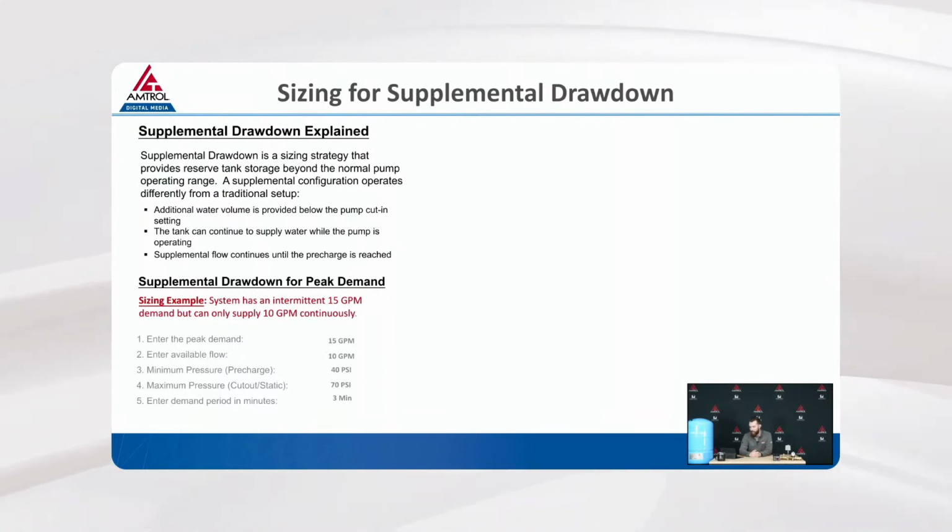And then you're going to have your max pressure, which for a city supply is just going to be your static pressure. If this was on a well or a community well or anything, it would be the high limit, the cutout pressure. Basically what you can see we're doing here is we're building our pressure gap. So we're going to have our minimum required and then our maximum given, and that's how we know how much room we have to work with. And it's going to give us our acceptance factor for those that are following along. So stay tuned.